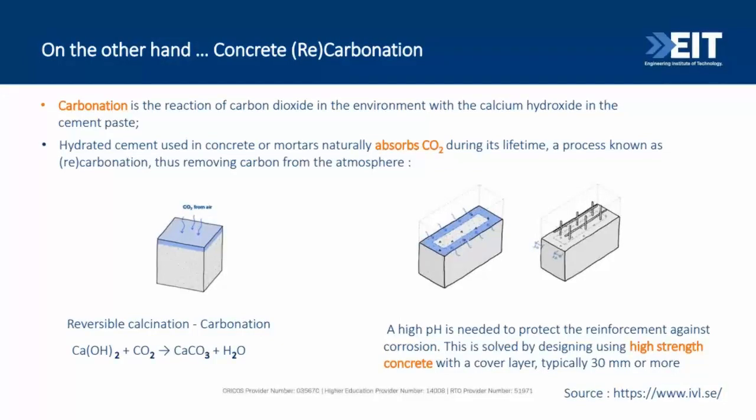So I want to think about this, because what's happening here? Carbonation is the reversible reaction. It's calcination, right? We have the carbon dioxide absorbed here, right? And we have the carbonation. So concrete will absorb, will store carbon dioxide. But over time, we need to be very careful with this alternative. It's something that we cannot avoid. It's inherent to concrete properties. It's all about concrete durability properties as well. But the literature is trying to balance this question, right? If it's good or bad for the concrete service life.